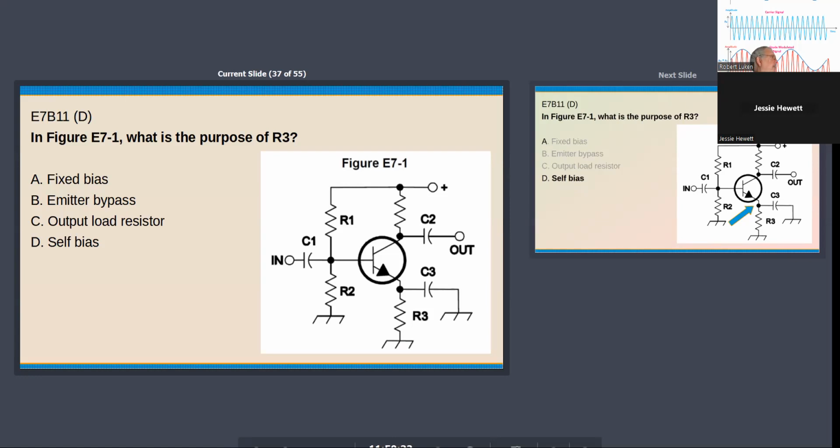So with no input, whatever voltage is set between R1 and R2 on the base then changes up or down with the input. If you have a varying input, a higher voltage conducts more and a lower voltage conducts less compared to the minimum voltage. Unless R1 and R2 are very high resistance values, you're selecting the midpoint between. If you want a variation of conduction that follows the input signal, you have to bias that somewhere between cutoff and saturation.